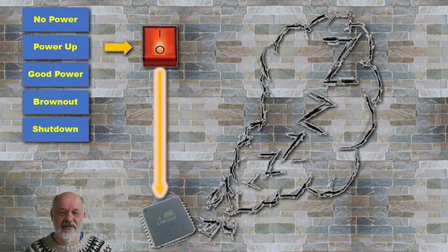Normally the duration of this state is only a few milliseconds, but if your design is not good, it will destroy something. It has happened to me many times that I didn't take good care of this state. This is probably the most harmful and the most dangerous state because all bets are off. They guarantee on these microcontrollers that they have the outputs in a specific state when it fires up.